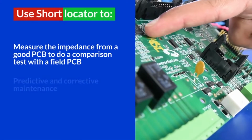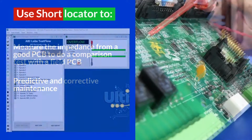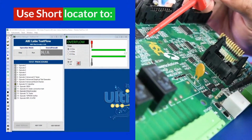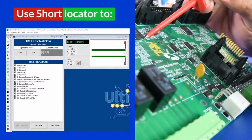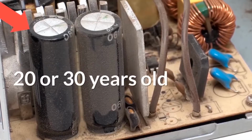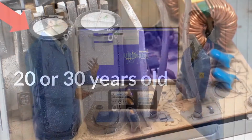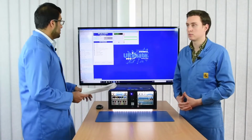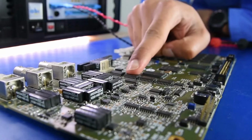You can also use it as predictive maintenance. If you can measure the same point every so often, you can see that slow degradation, and maybe that gets oxidized over time, and then it increases the impedance. Perfect. So like you just mentioned, you can measure the difference in impedance between a good board and a board that's been in the field for a long time, let's say 10, 20 years. Exactly. Right, great. So that was episode 6.